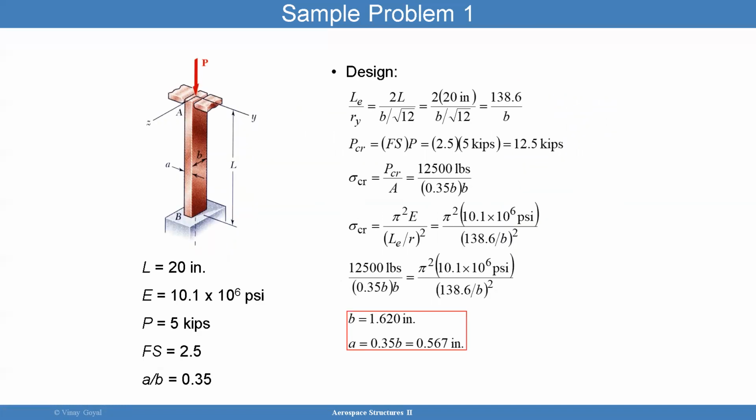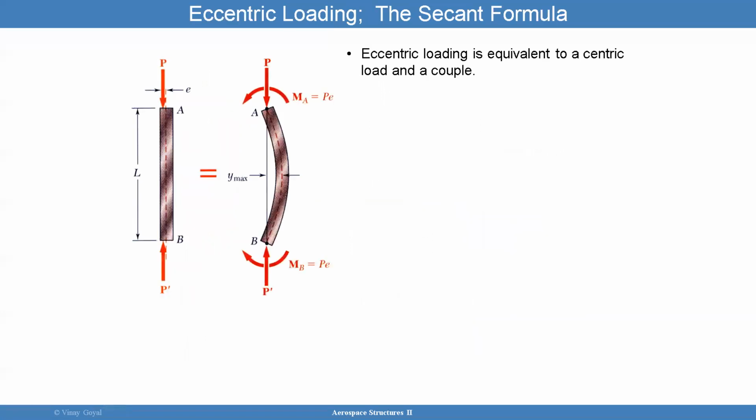Yeah, and then from here you just apply a factor of safety to the load, and from there calculate where the buckling could occur and what dimensions can actually take you all the way to the buckling load. And here they're using a factor of safety of 2.5. We're going to see later on that for other applications, the factor of safety can be lower than that.